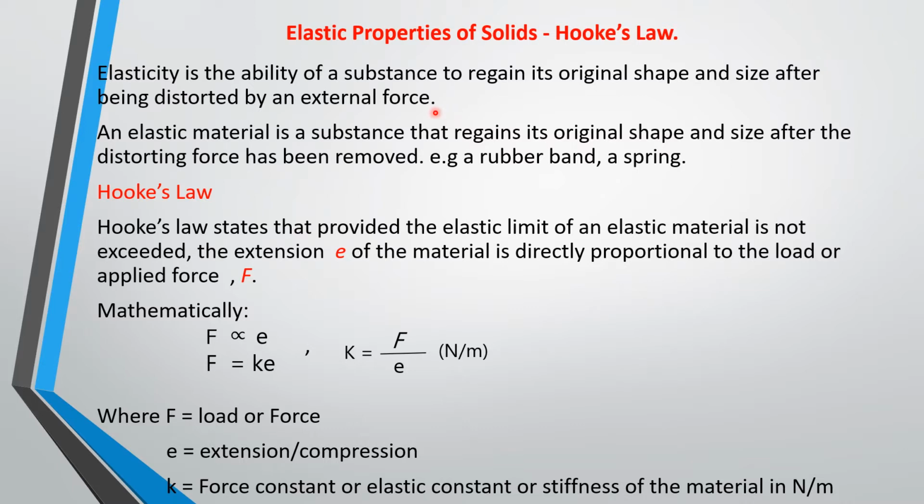If you stretch your rubber band, if you don't overstretch it, when you release it, it will return back to its original length, right? The same thing applies to a spring. If you extend a spring up to an extent, it can return back to its original shape or original length. That ability for the substance to return back to its original shape or size is known as elasticity.